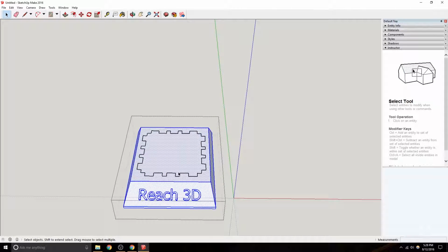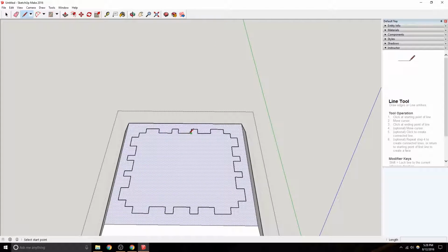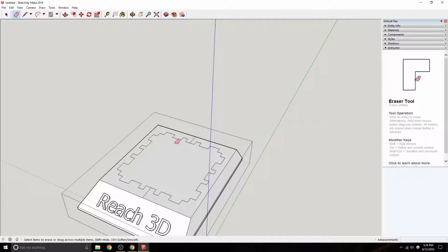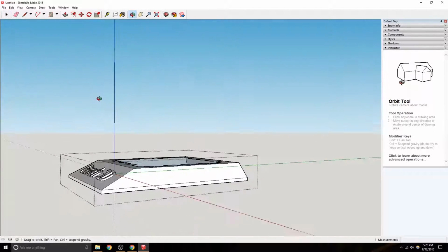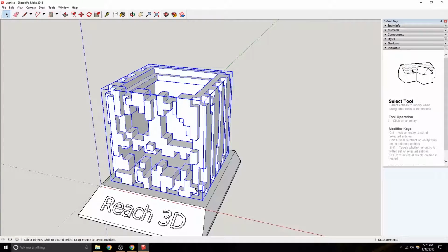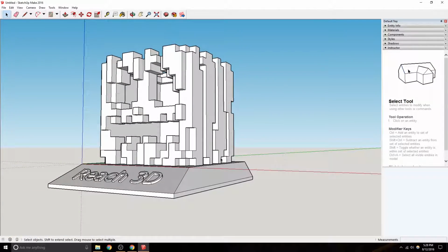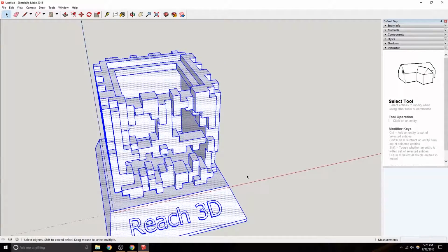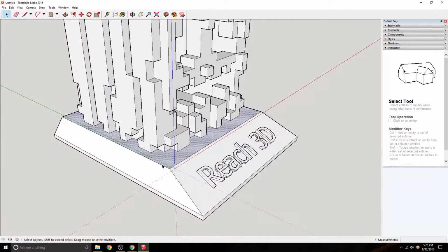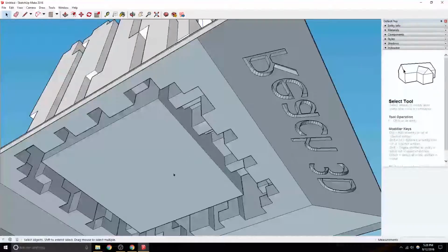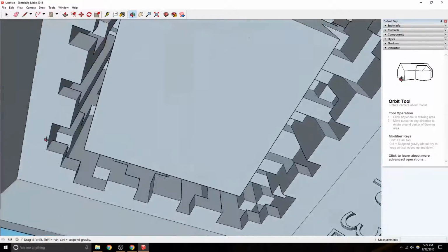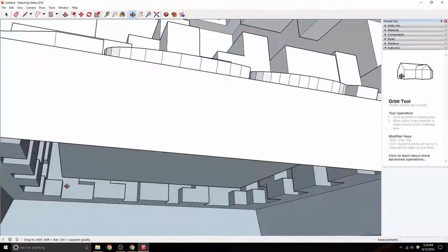We're going to explode that one too. Connect it to the 2 edges. Remember how we discussed how Google Sketchup sometimes won't attach those lines to the edges, and it does that. So you just got to draw a line. So once we got that opened, and we've got this guy opened here, they're pretty much connected. All we've got to do is just explode both of them, and you are done. So yeah, this is a pretty simple shape, but you can double check that they're merged. As long as there's no gaps or you see any dark lines, these definitely should be identical.